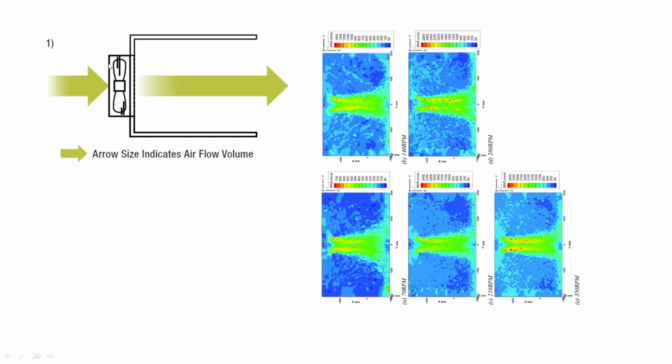I mean, it's correct in a way, but it doesn't give you the true idea of how it is in a case design. So you have a fan, it's the same size as the tube. You blow air down the tube, and if a fan has a tendency to blow air off to the sides, it has nowhere to expand because this fan is the same size as the tube. So this means that the air is going to travel down the tube anyways. Mind, the air is still trying to go sideways, so it's just going to bounce off the walls and create a larger boundary layer. So a fan that tends to spear off to the sides will tend to have lower performance than one that has a nice concentrated airflow.